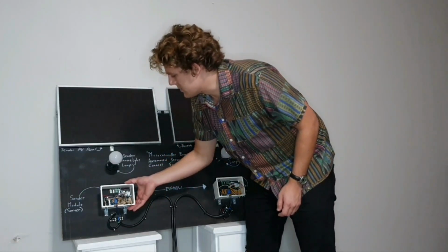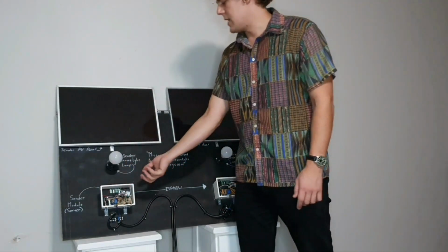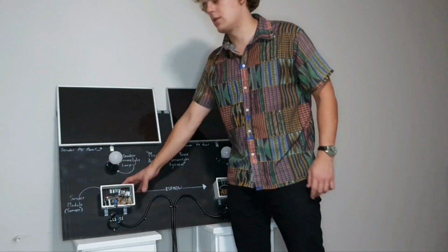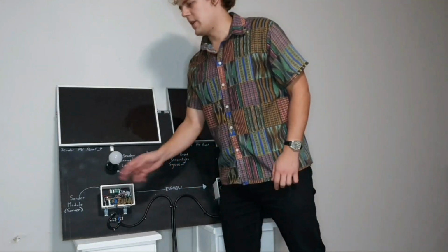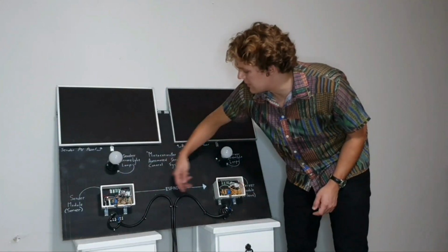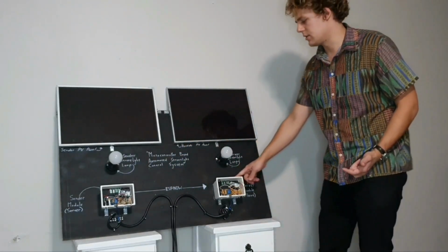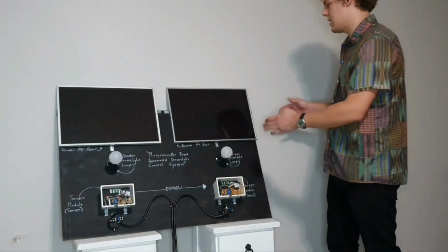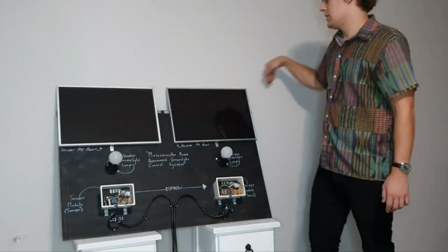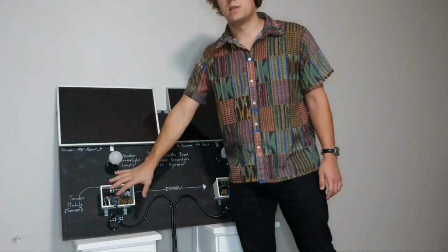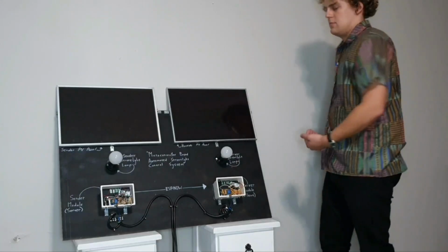Once this system senses that the absence of light has reached a certain threshold, the day-night switch will activate, and it will tell this microcontroller to close the relay, and the light will go on. And also at the same time, a signal is sent wirelessly via ESP-NOW to the other ESP8266 NodeMCU microcontroller in the receiver unit. And we can have up to 20 of these receiver units. So in other words, we can have one sender and 20 other street lamps working from this one day-night switch. So this signal can be relayed then to 20 other street lamps.